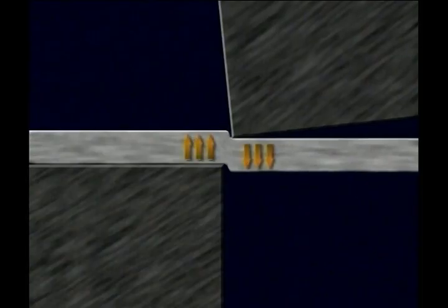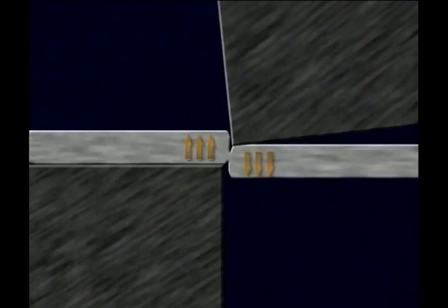As the blades come together and contact the workpiece, they partially penetrate the material. This builds up opposing forces in the stock. A crack or tear called the slip plane then develops on both sides of the material, separating the stock. The shear blades typically penetrate the stock no more than 1/3 of the stock thickness before the slip plane occurs. The exact amount of penetration varies with material hardness and knife clearance.